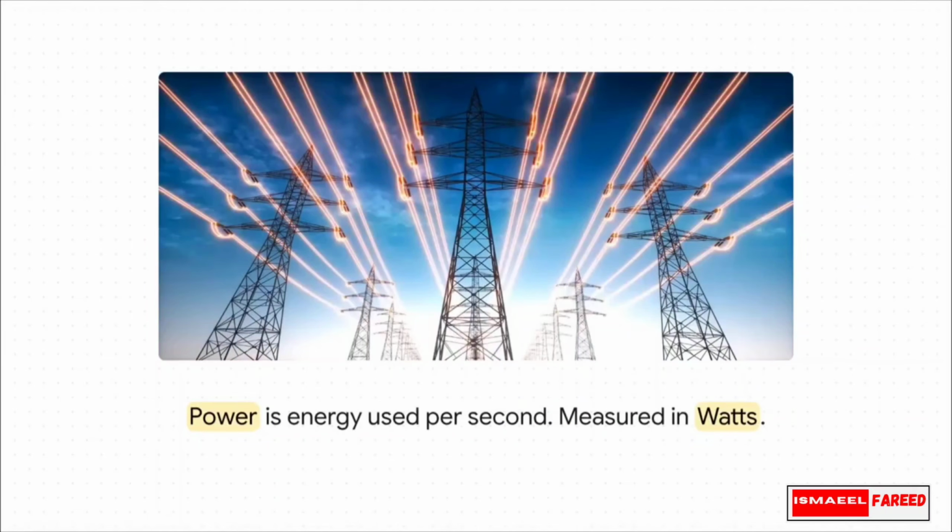And that naturally brings us to electrical power, which is the actual work getting done in our circuit. Power is calculated just by multiplying voltage by current. It represents the total energy being used every single second, and it's measured in watts. This is a massively important metric for anyone tinkering with electronics because pretty much all physical components have a maximum power rating. If you push too much power, too many watts, through a part that just can't handle it, that energy theft we talked about will generate way too much heat, and you run the very real risk of literally burning your parts to a crisp.